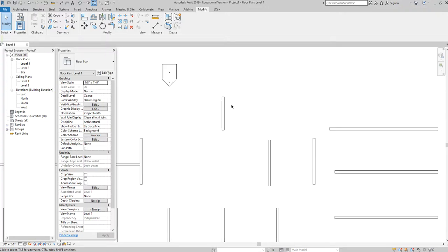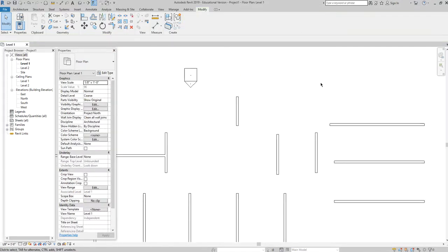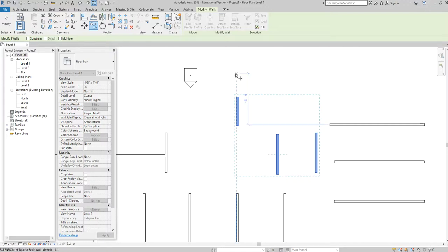All right. Copy will allow you to take one object and make an identical copy of it, either a dimensional distance from the first one or by eyeballing it, right? By kind of free-handing where it goes. So again, I like to select the object I want to copy. You can copy anything in Revit, doors, windows, walls, roofs, furniture, anything you want, just like in AutoCAD. I'm going to select the object or objects. I can do more than one at a time that I want to copy. And this little guy right here is the copy command. Click. Okay. I can click to specify a base point.